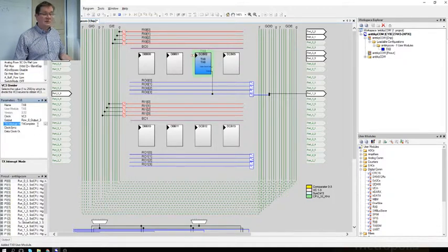Okay, so transmission complete would trigger an interrupt, which means that basically you can make a series of data transmissions, for example, sending a string byte by byte in an interrupt service routine. Okay, then the clock sync, as usual, use sync to SysClk unless it says something else on the datasheet.